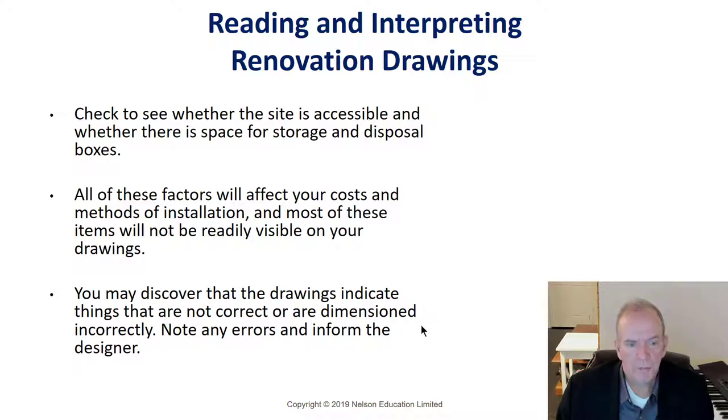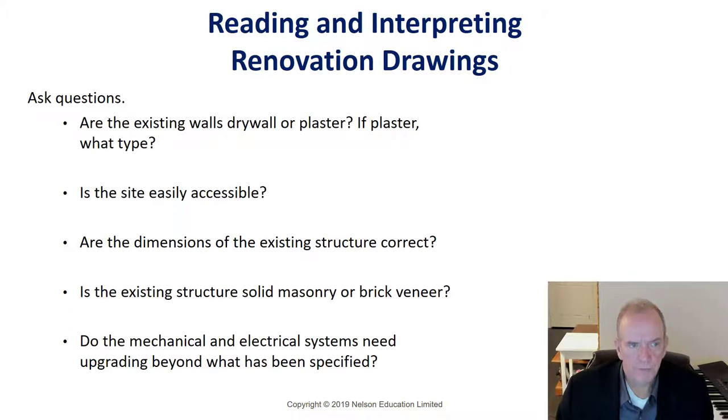And also, don't assume the drawings are correct. I've rarely seen drawings correct in renovations. So you've got to do your own measurements. Consultants sometimes make mistakes with measurements. So, you know, some example questions: are the existing walls drywall or plaster? Is the site easily accessible?